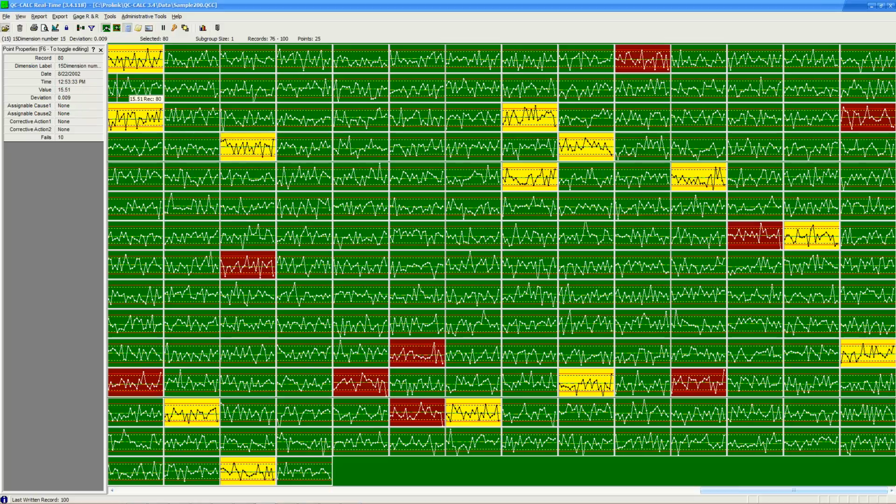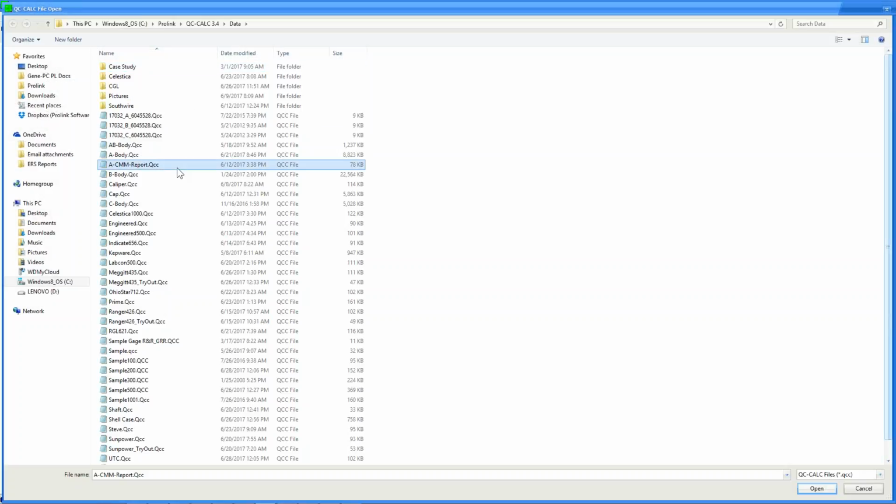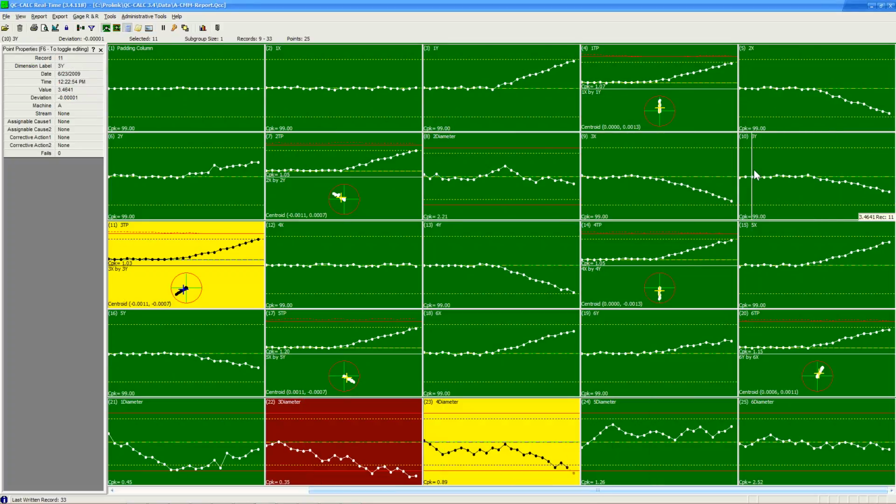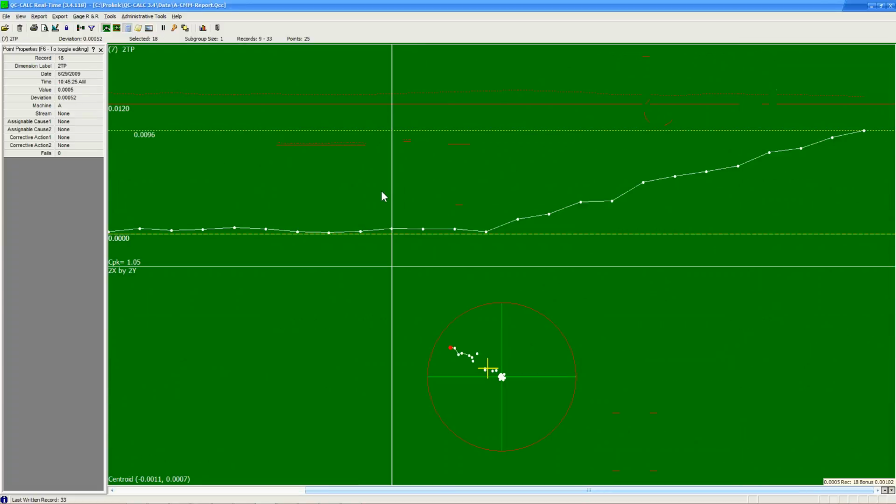Thanks. One other thing that is important that I should mention, I assume you may have some true positions that you measure. Here's a set of data that came from a CMM. You'll note that it has an X position of the hole number 2, a Y position, a true position and a diameter. And we can do a consolidated display like this, which is showing the deviation of true position, but it's also got a target chart down here that shows the X and Y relative deviation, so that this last red dot is the last point. That's the same last point up there. And it's very clear and very easy to understand this is going negative X and positive Y.